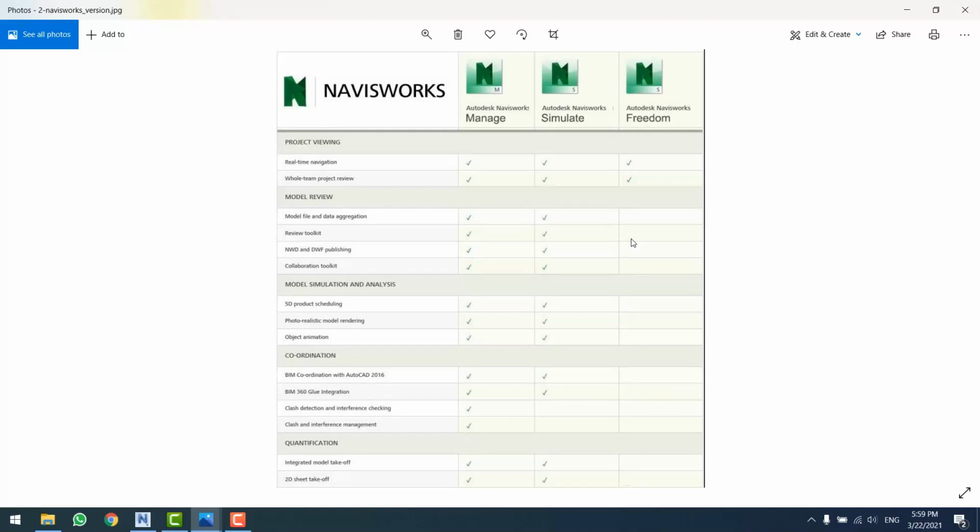And here let me give you a point. While you are changing your operating system or installing the softwares, I recommend you to install Navisworks last, after other softwares are installed. If you do this, Navisworks will install the required plugins on other softwares like Revit. On the contrary, if you first install Navisworks before installing Autodesk Revit, after that you have to install the plugins yourself. In other words, you will have some problems. So note that Navisworks should be the last software installed on your device.